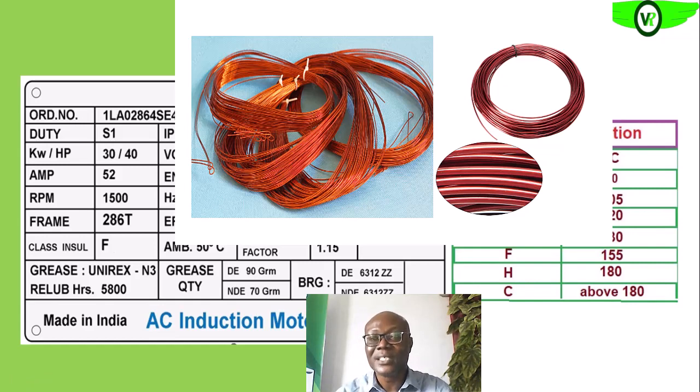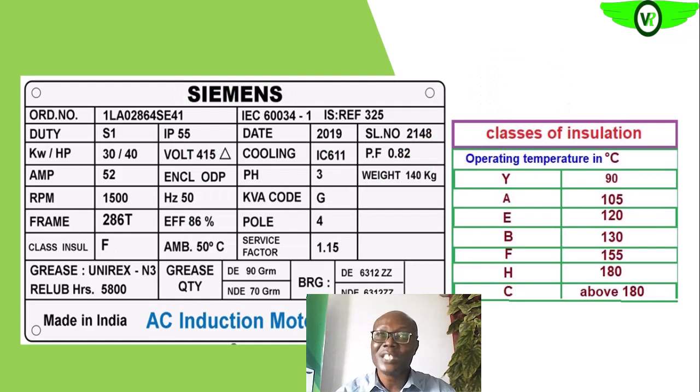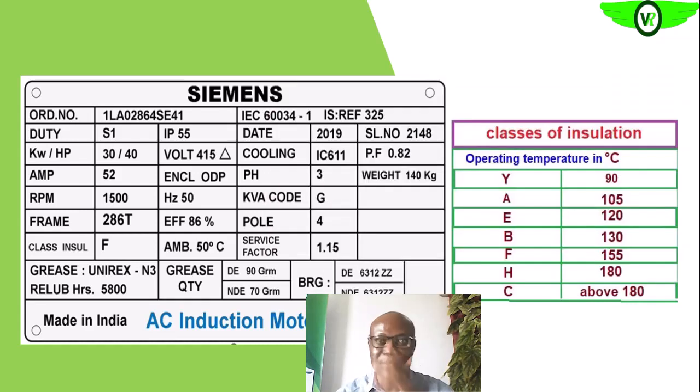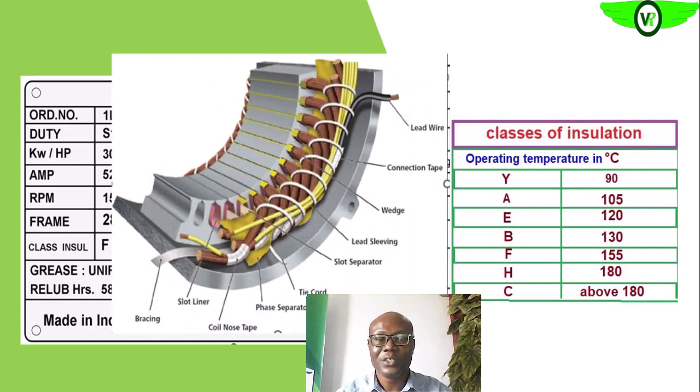Are we getting it? Then the insulating lead rod and all the insulators that we are going to use are designed for class F, because if it is perchance subjected to more stringent operating conditions, your equipment will be safe for you. But if you use a lower class material, that would definitely affect the integrity of your machines.